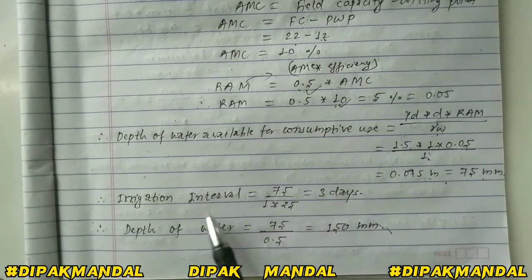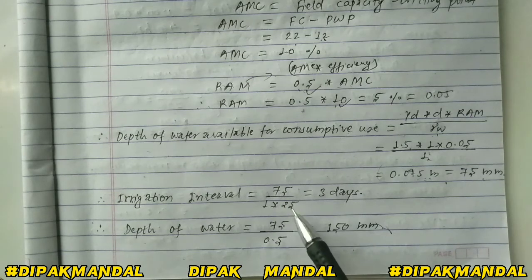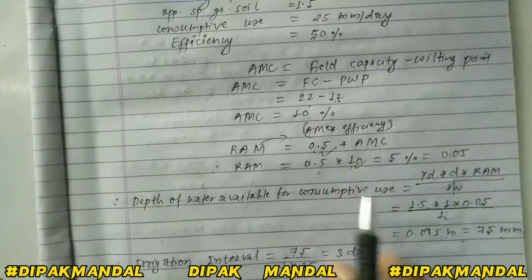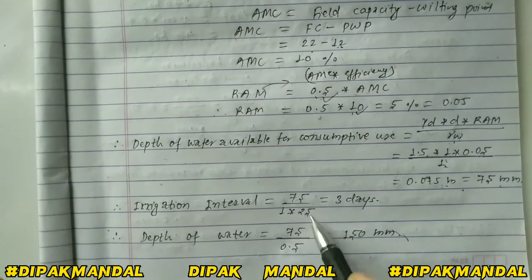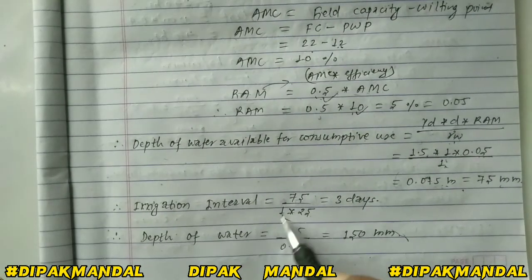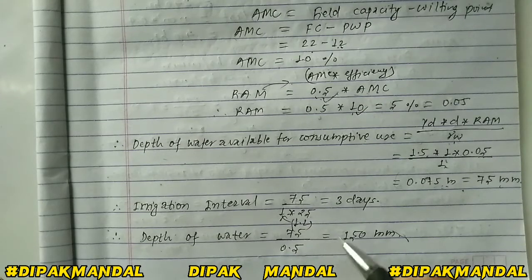We take the 75, the calculated depth of water available for consumptive use, and divide it by the consumptive use, which is given here as 25 mm per day. We have to divide by this value, and multiply with 1. Sometimes we have to multiply with 1.2, that depends on the condition, and you can simply take 1 or 1.2. So after calculating this value, we get irrigation interval equal to 3 days.